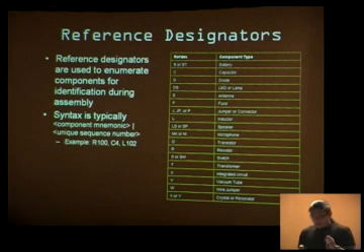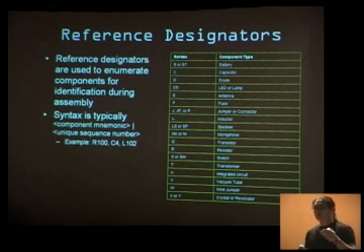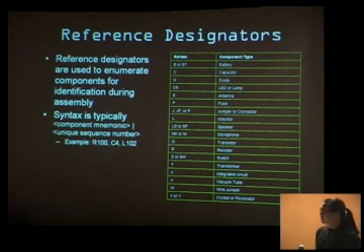The important thing to keep in mind when you're reading a schematic is the reference designators. They also apply the reference designator on the circuit board. So if you're looking at ambiguous components, like is this a transistor or a diode, they'll have a little piece of text next to them. It may say D100 or Q100. If it says D100, it's a diode. If it says Q100, it's a transistor. So you can use the reference designators to give you a cue as to how to reverse out the particular component as well.